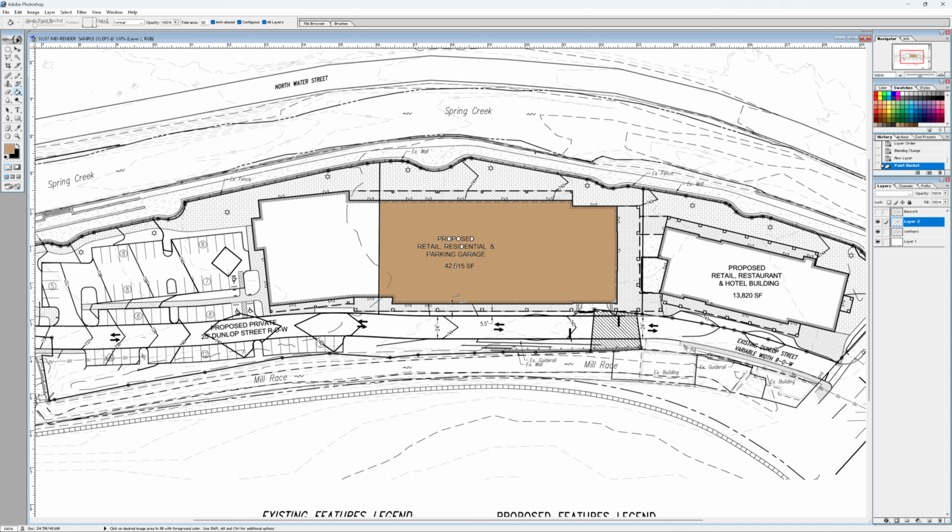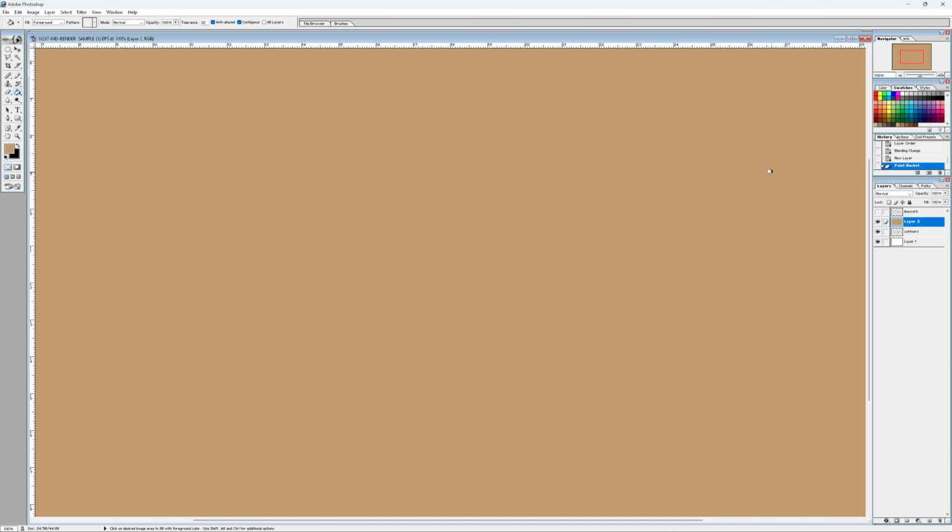So if I undo that and uncheck this, the whole screen becomes brown. So this is a key for really rendering and putting down color quickly. You need to have all layers turned on. The problem is, you need to make sure with contours, they could be blocking off part of the area that you want to have rendering. And therefore it won't be contiguous, and the color will stop there and you'll have to click a lot more times.